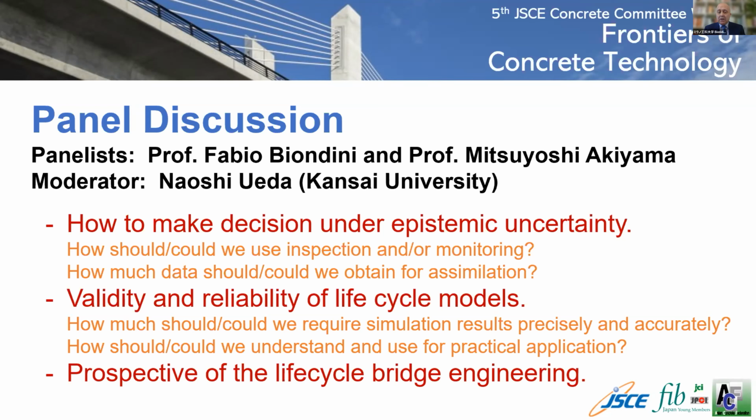Another aspect, if I can mention this in addition to these comments, is related to the level of complexity in the life cycle models. We need to make these models as simple as possible, but we cannot neglect complexities when they are present in the problem. I make an example. We typically use the Fick diffusion equation to model chloride ingress using the one-dimensional solution, the one-dimensional form of Fick diffusion.